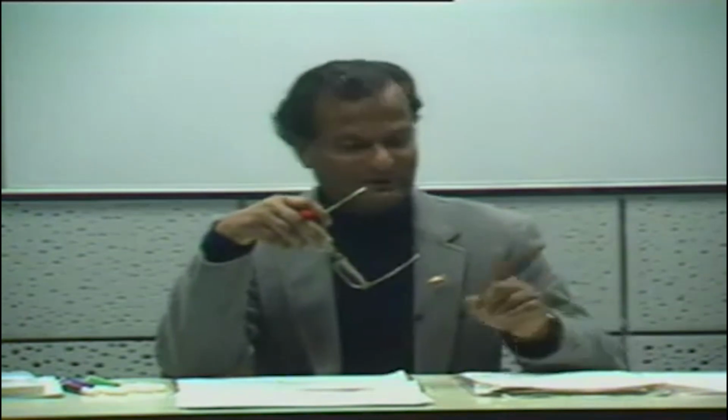That's right. It takes quite a bit of time. The needle goes on oscillating, and then finally it settles to some value. Whereas if it is critically damped, then it reaches the final value. All right. If it is over damped, then it takes a very long time to reach a steady state, and therefore these concepts are important.